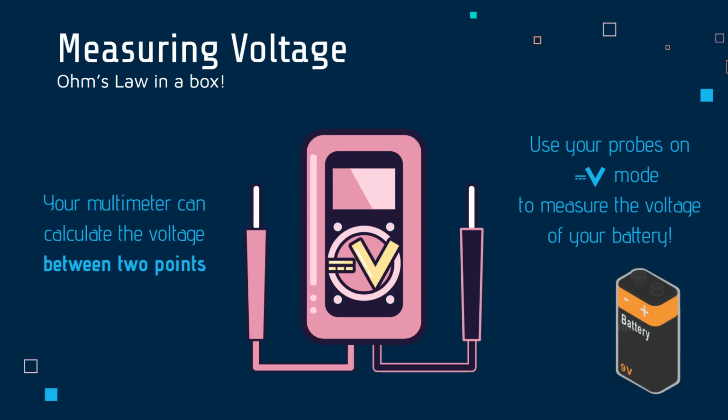What did you find? You may know that this battery is commonly classified as a 9-volt battery. But was your battery's voltage exactly at 9 volts? It so happens that a fully charged 9-volt battery typically sits well above 9 volts, sometimes getting close to 10 volts. However, a battery that has been drained past 8 volts is typically considered dead.